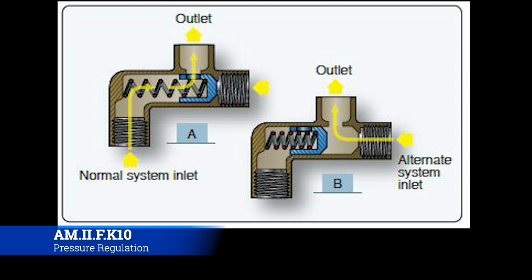Well, in the event of an emergency or a systems failure or any number of situations, you need a way to turn the failed hydraulic pump off and open up a valve for the working hydraulic pump or the RAT or whatever, and the shuttle valve is how that happens. So just keep in mind that as we go forward, whenever we're talking about redundancies in hydraulic systems, the shuttle valve is really the linchpin for how that works.